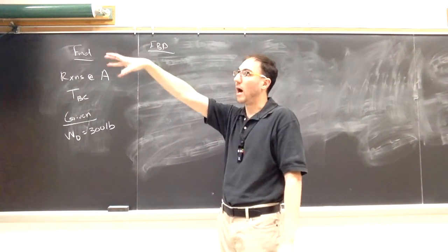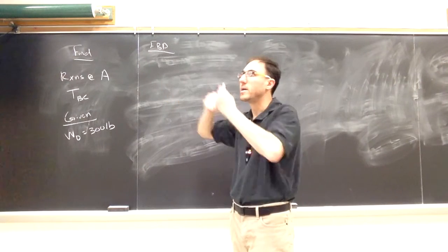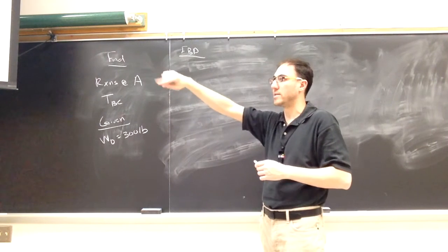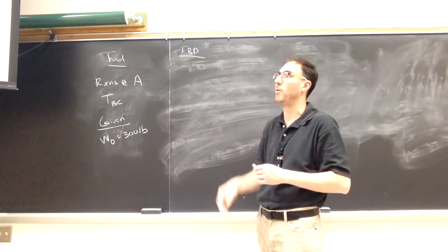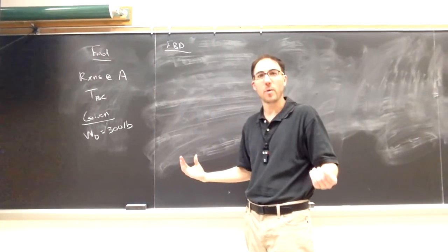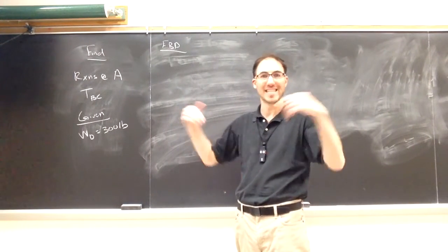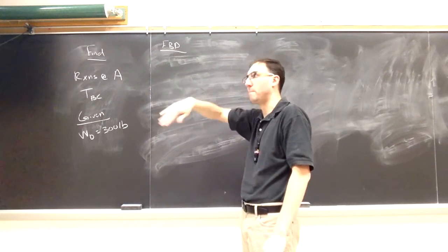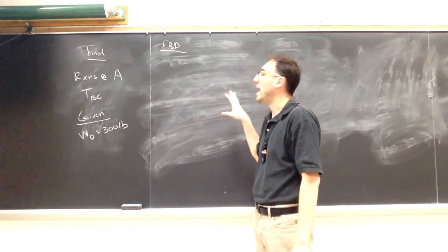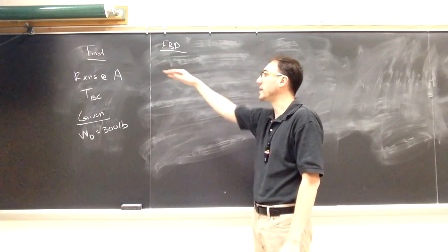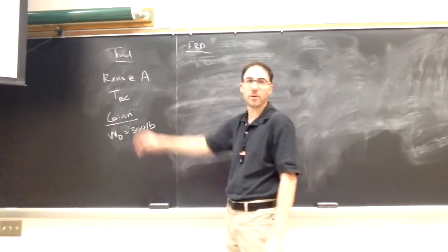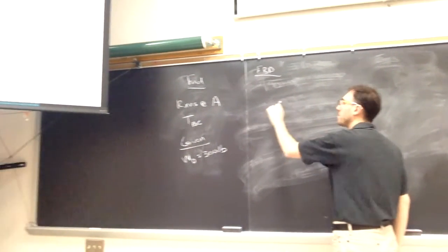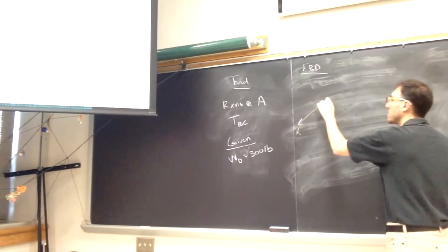Right, so if we isolate that blue rod, we're going to disconnect it from those brackets at A. We're going to cut the weight away. We're going to cut the rope away. Everything we remove, we then have to model what the things we removed did to the object we kept. So if we just keep that blue bar from A to B, kind of that T section, and use that as our object, we're going to see the reactions at A come through, and we're going to see the tension in BC.